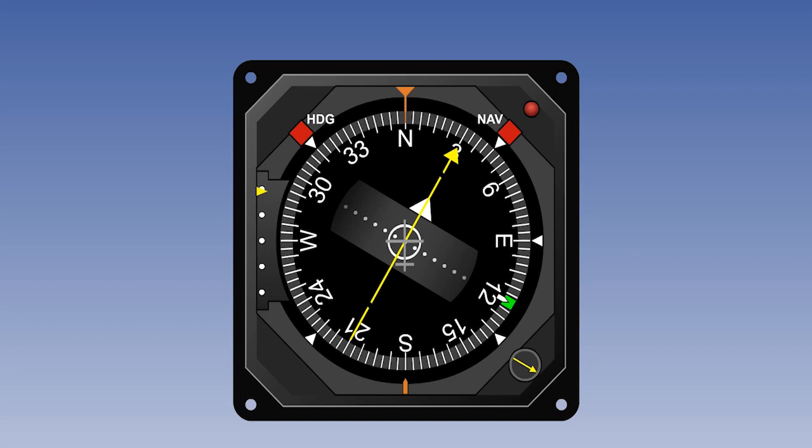Nevertheless, if no INS is fitted, on a typical modern airline quality gyromagnetic compass, the gyro drift rate will still only be about 1/10th of a degree per hour when operating in DG mode. In this case, real drift is low enough to be insignificant.